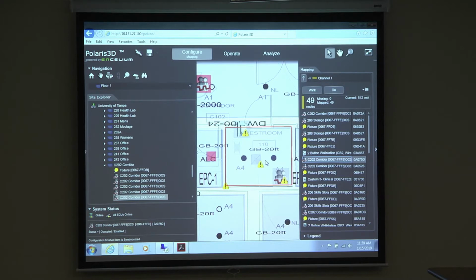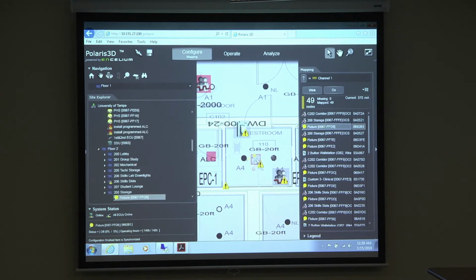So when we come to site, every device here that's connected is all grayed out. And once you trigger them, click on them, they make reactions. So if I trigger a module, the lights flick off and on. And I click that module and drag it onto the representation of the module on the floor plan. And that's how you link both the device and the actual floor plan. Once you save it to the server and you configure it, then the ECU now captures that information and then it starts to work, right?